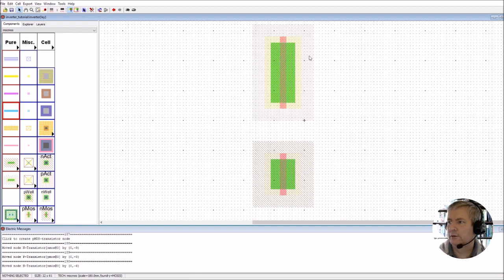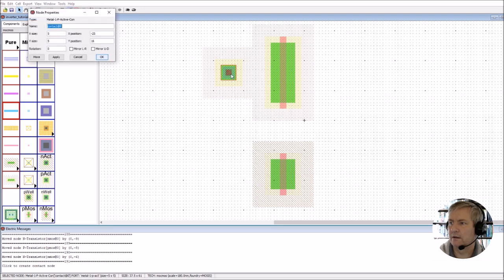Now in order to work with this PMOS device, we need to get the access to the active region. So we're going to create in effect what would be the contact through to our source and our drain. So we've seen this whenever we developed the PMOS and NMOS transistor in a previous video. So we need the access to this active layer. So it's this P active. So we're going to get P active here, and it has to be the same size as this. So we'll make it the 20.